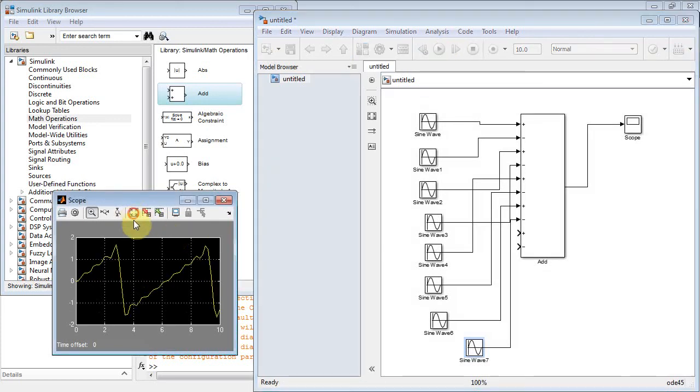Wow, look at that. We're starting to get a nice little triangular wave. Actually, more like a ramp. It ramps up, drops off, ramps up, drops off. And we've only implemented the first 1, 2, 3, 4, 5, 6, 7, 8 terms. So we have the fundamental and then 7 higher harmonics. Of course, the series goes to infinity, and when you do that, you're going to get straight lines and really nice sharp edges. The nice sharp edges come from high frequency terms.